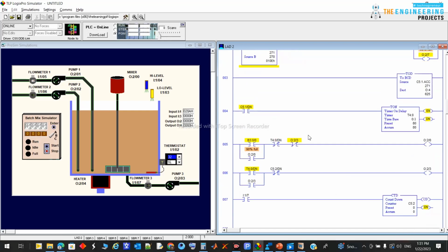So now, guys, I just made the TON timer to count the time once reaching the 90%, which is the done bit of the counter for the filling tank counter from the signal of the volumeter 1, and then I just count for these 8 seconds. So these 8 seconds will stop the mixer, and also after stopping the mixer we need to run this pump.